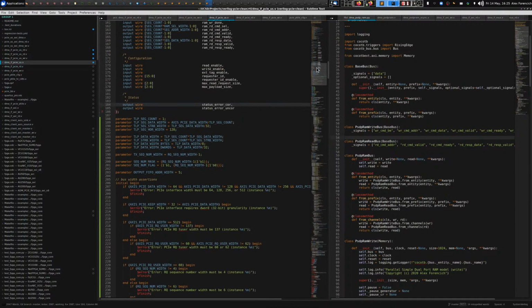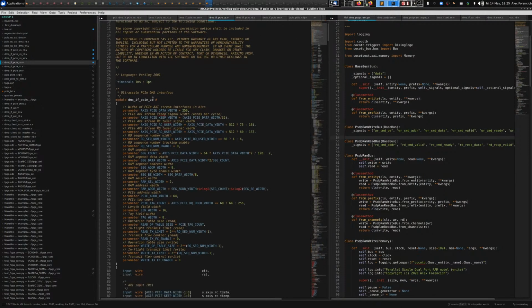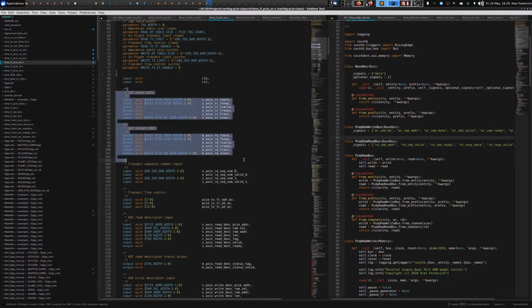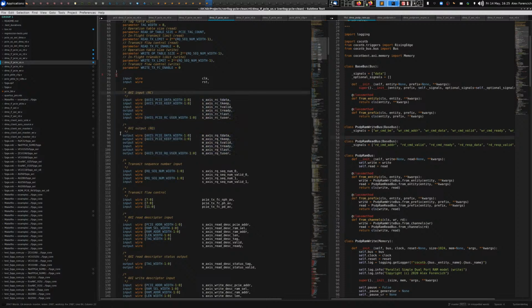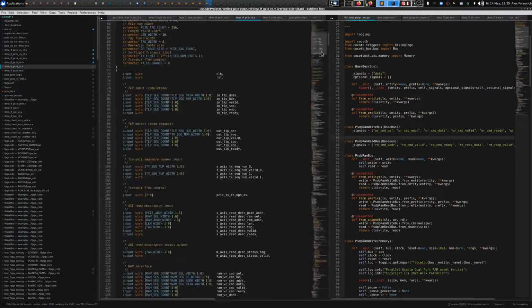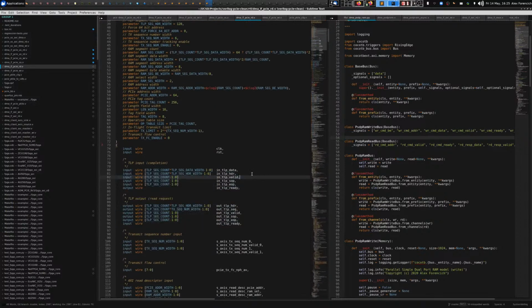So this is, if you want some more details on the PCI Express stuff, the UltraScale version here. UltraScale PCIe DMA interface. So this has just an AXI stream interface coming and going, basically. This connects to the RC and RQ, and then the CC and CQ, you use different modules for that. I guess I don't have a top level for this one yet. I just have the separate read and write modules. But this is the interface that I've been working on for the generic module.